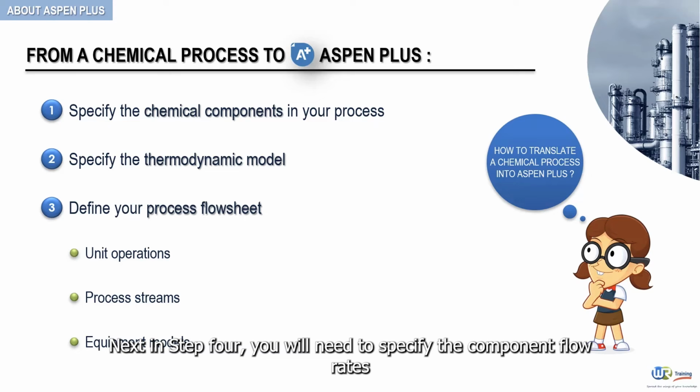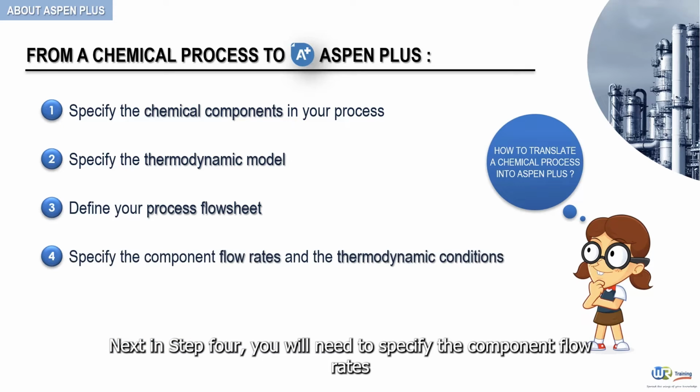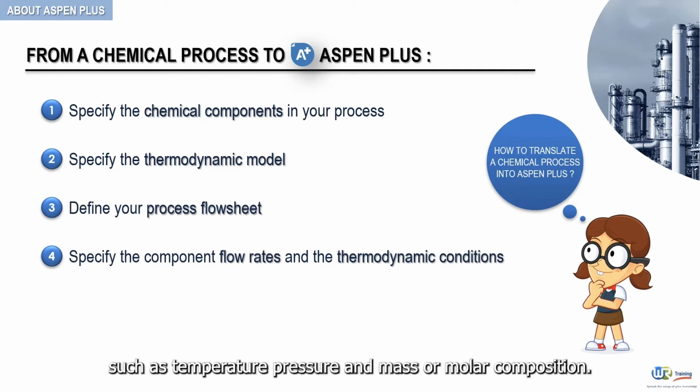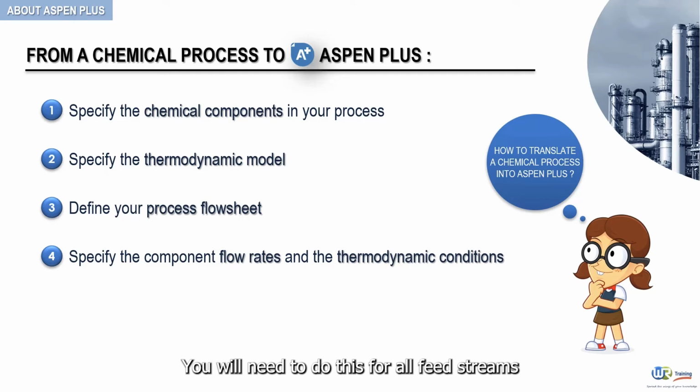Next, in step 4, you will need to specify the component flow rates and the thermodynamic conditions, such as temperature, pressure, and mass or molar composition. You will need to do this for all feed streams.